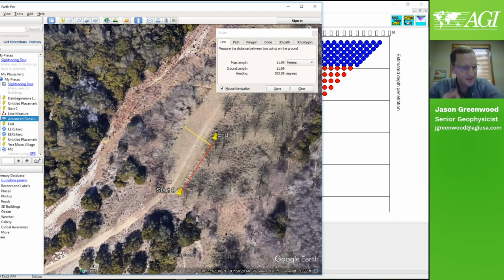It's just the very first line's 15 minutes. And I would recommend for 56 electrodes, 2 to 3 people. And one of those people should be trained on data inversion, and the other 2 don't necessarily have to be experts on the processing, but someone should be able to do some field QC or be in close contact with someone on the office side to do that field QC.